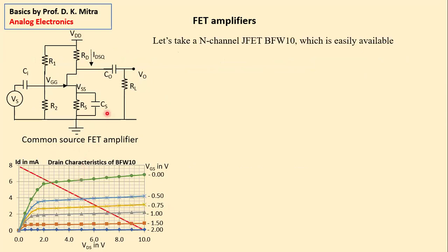Firstly, as I said, I'll give you a guideline. Take an N-channel JFET because there are so many FETs. Which one should you take? I say this is the easiest, simplest and sturdiest one. That means you cannot damage a JFET so easily. But with a MOSFET, a little bit of mishandling or a hit in soldering the MOSFET leads will damage the MOSFET itself.